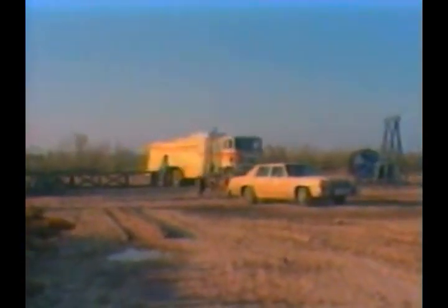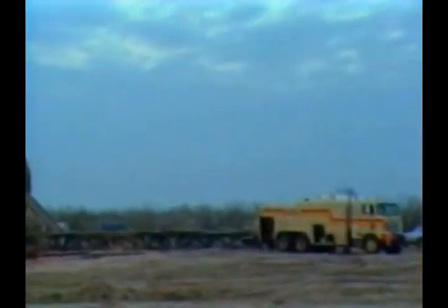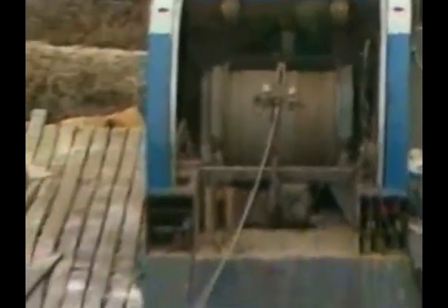The preferred location for setup and logging is for the logging unit to be in a backed position, beyond the pipe rack, and accessible to the end of the catwalk, with an unobstructed view of the rig floor. This location provides the logging crew with the workspace needed to lay out, assemble, and test the logging tools. It places the logging truck and winch operator in favorable alignment with the derrick floor and allows the visibility of all personnel throughout logging operations.